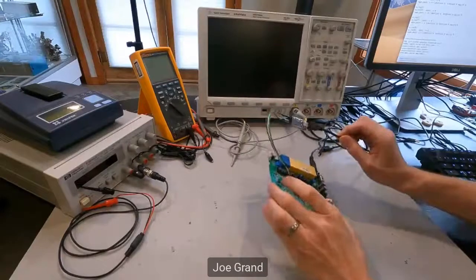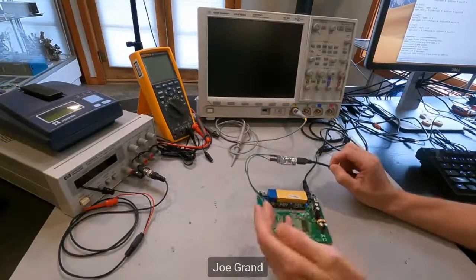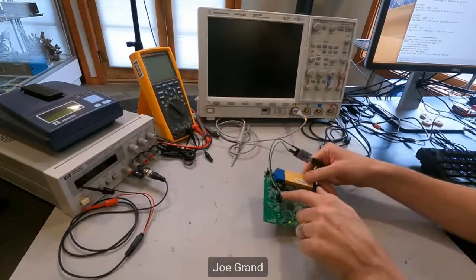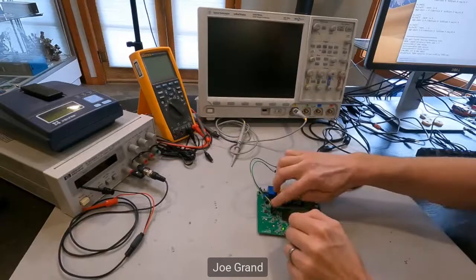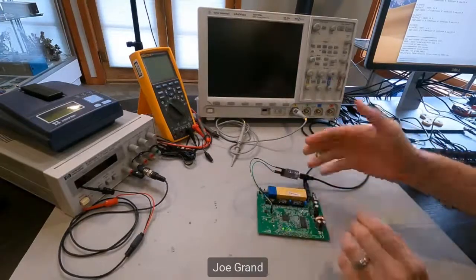So that's the setup. It's pretty easy. I have my ground connection, and then I have my transmit and receive pins. If you don't know which pin is which, generally a UART interface is going to be pretty easily identifiable if engineers put it in an accessible way. You usually see a 4-pin connection for the power line or system voltage line, ground, transmit, receive.